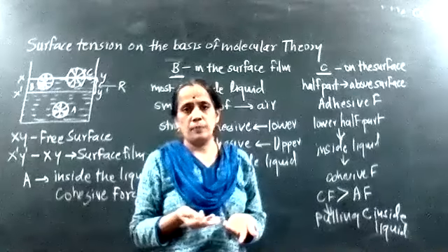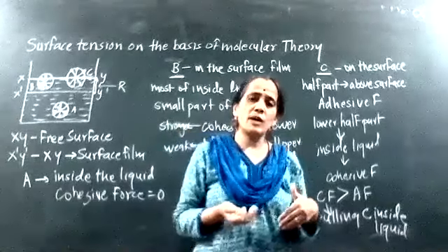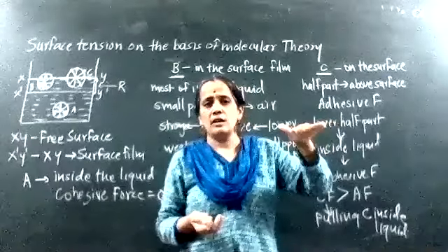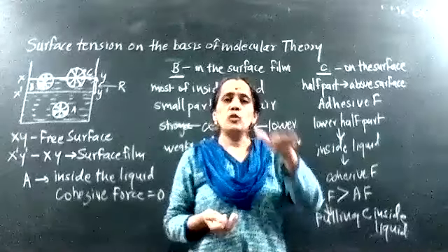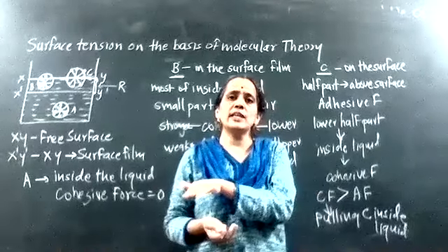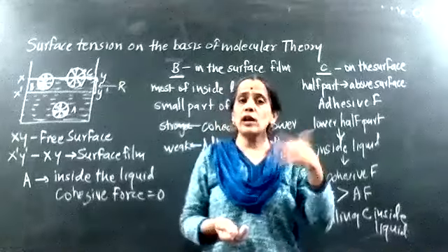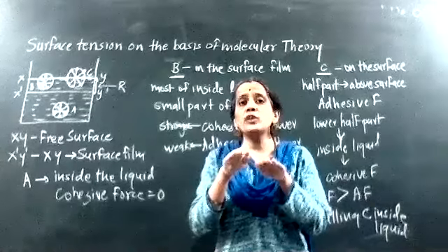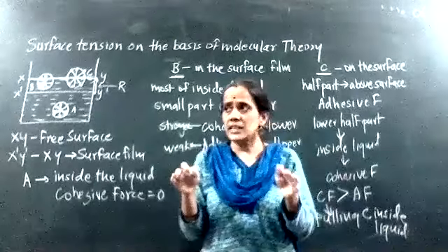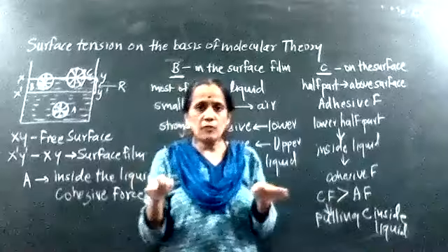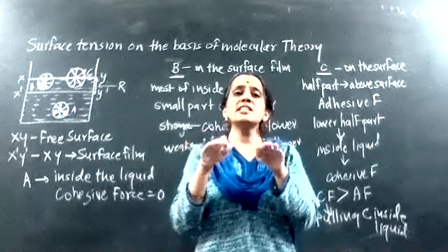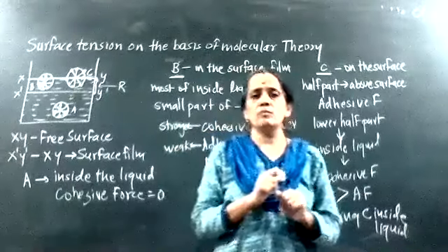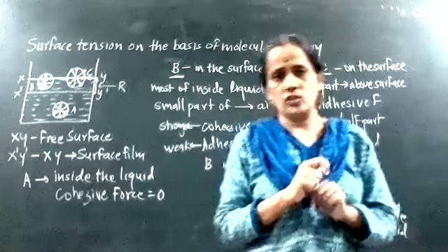surface tension. So why does the term surface tension come there? All molecules which are present on the surface have a tendency to move or be pushed down inside the liquid due to more effective cohesive forces. So the surface area is trying to minimize itself. Therefore, it will remain like a stretched membrane, like a membrane under tension. And that is called your surface tension.